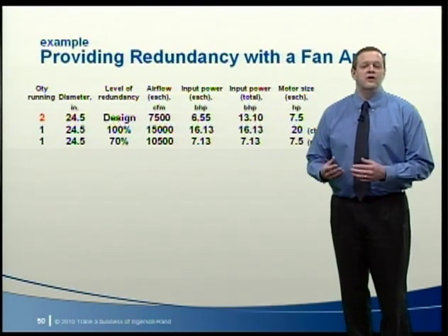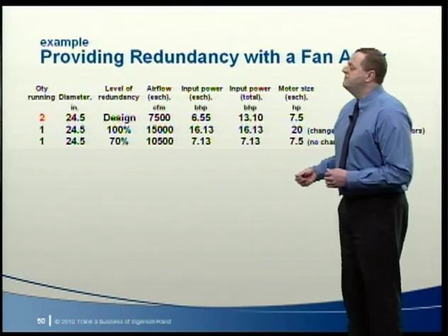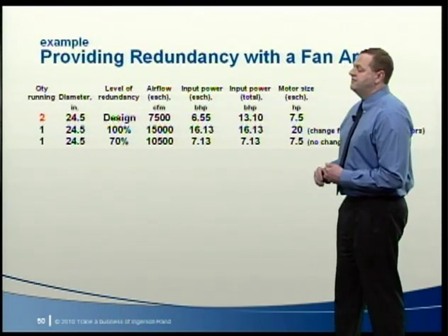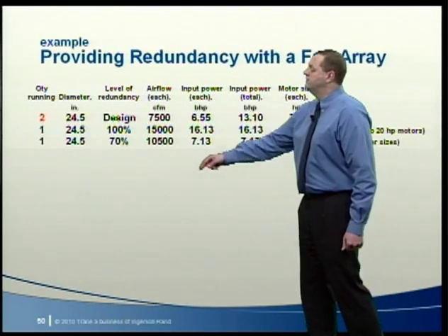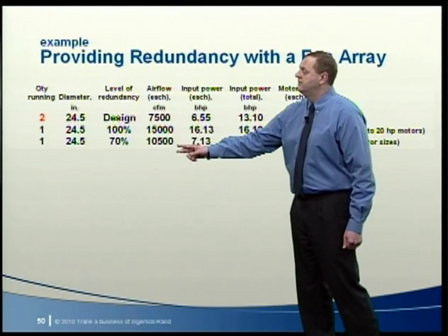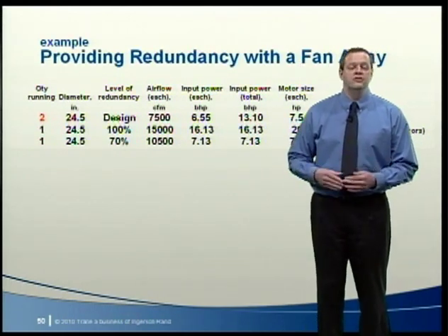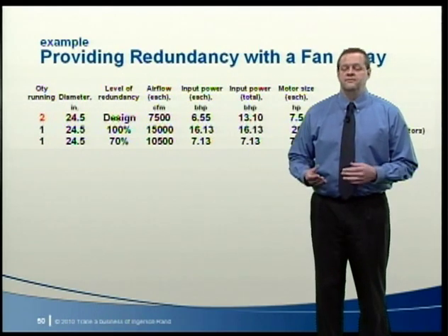Now, as a side note, what happens if the motor sizes are not increased? In this two-fan array, if one fan fails, the remaining fan is capable of delivering up to 70% of design airflow. So if 70% is an acceptable level of redundancy, you wouldn't need to upsize the motors.